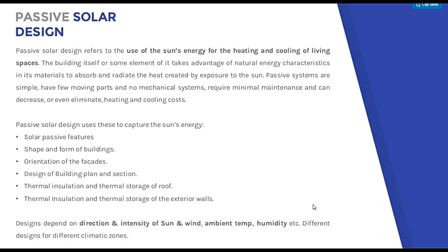What is a passive solar design? Passive solar design refers to the use of the sun's energy for heating and cooling of living spaces. The building itself or some element of it takes advantage of natural energy characteristics, its materials, to absorb and radiate the heat created by exposure to the sun.